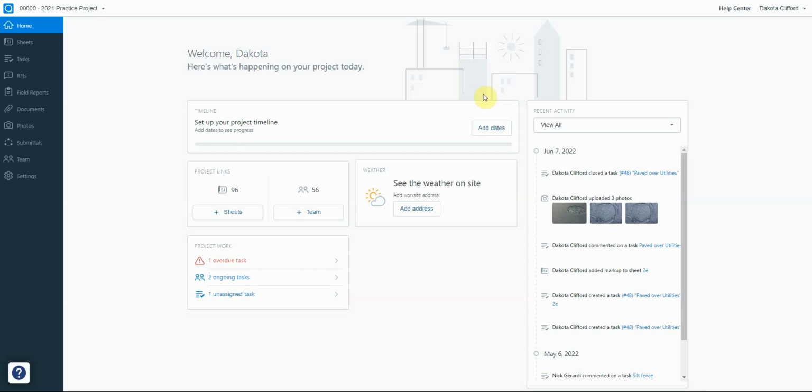So the first thing, of course, that we're going to do if we have an issue come up on the project is identify the issue and then notify the project team as appropriate. That should include, depending on who identifies it, the senior inspector on the project, the construction manager, and the area construction engineer, depending on the severity of the issue. We're also going to make a decision on whether or not an NCR needs to be issued. That should be a project team decision. And then if one is issued, we're going to go through the process that I'm about to outline here.